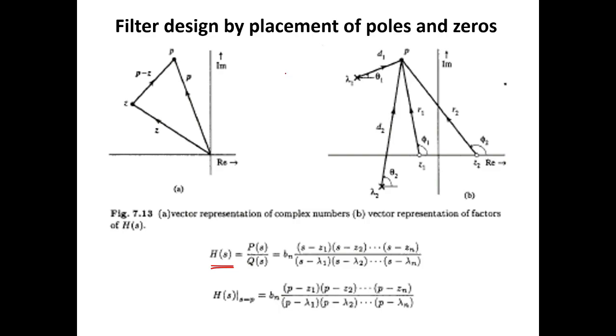If you remember correctly, take the example of, say, a non-inverting amplifier, with V in and V out, and resistors R2 and R1. I hope everyone knows this circuit, whether from biotech or biomedical, it doesn't matter. So we get V0 equals 1 plus R2 by R1 times V in.